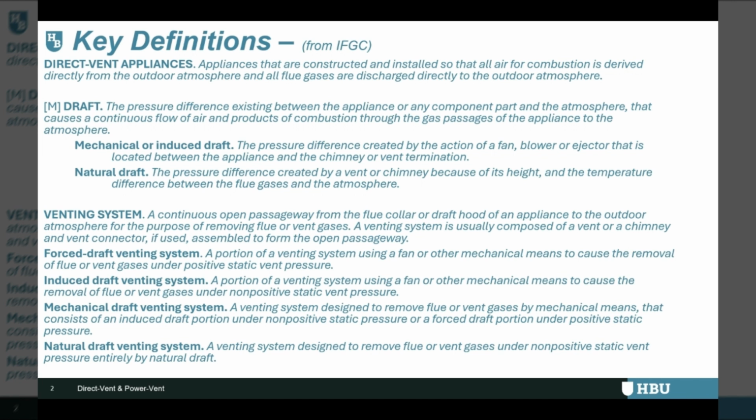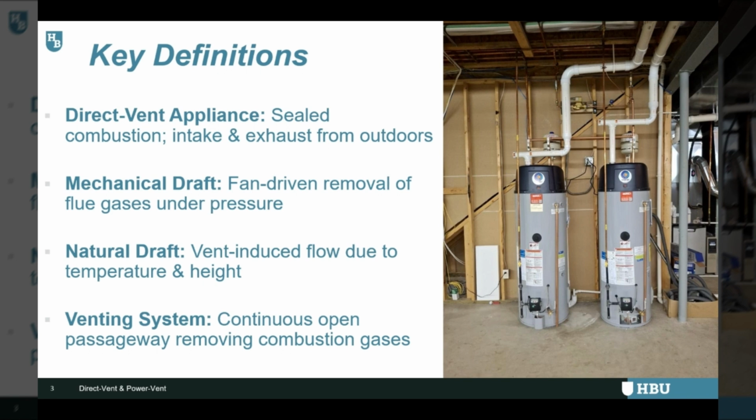All right, I'll give you a couple seconds here. You can pause this and go ahead and read what the definitions directly out of the codebook have to say. Now, definitions are critical because we've got to make sure that we're speaking the same language here. So I just pulled a couple quick ones. Direct vent appliance, sealed combustion, intake and exhaust from outdoors. Mechanical draft, fan driven removal of flue gases under pressure. Natural draft, vent induced flow due to temperature and height. Venting system, a continuous open passageway removing combustion gases.